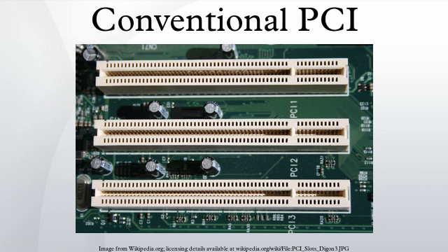Address phase: a PCI bus transaction begins with an address phase. The initiator, seeing that it has GNT and the bus is idle, drives the target address onto the AD[31:0] lines, the associated command on the CBE[3:0] lines, and pulls FRAME low. Each other device examines the address and command and decides whether to respond as the target by asserting DEVSEL. A device must respond by asserting DEVSEL within 3 cycles. Devices which promise to respond within 1 or 2 cycles are said to have fast DEVSEL, or medium DEVSEL, respectively.